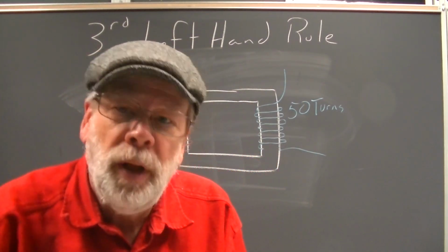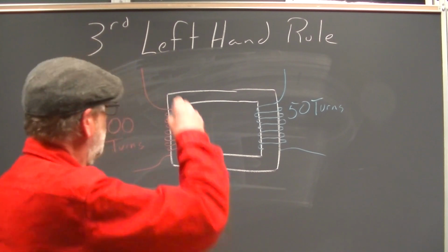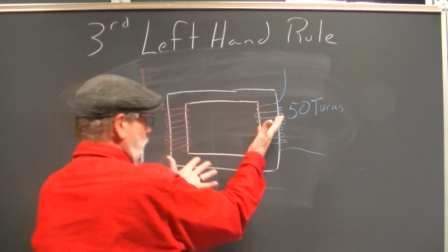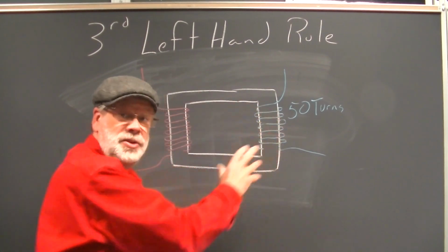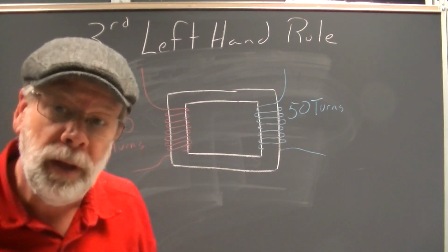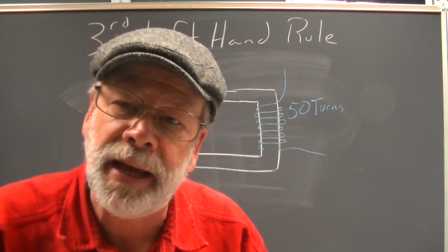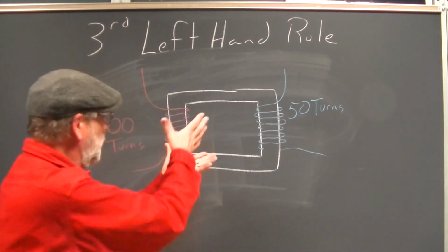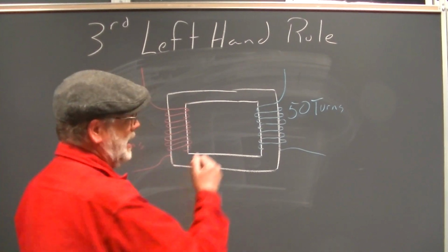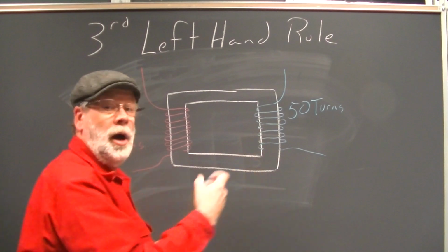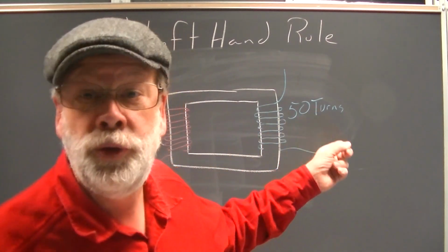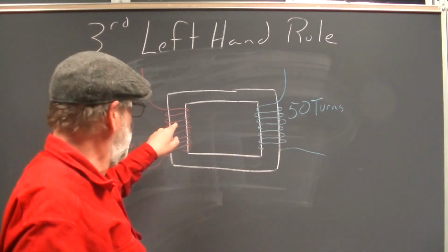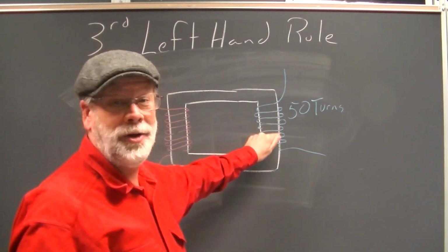As we get our first pulse of AC here, the current is coming this way, and we generate a magnetic field that wraps around, and as the magnetic field passes through that secondary coil, it generates a current in the secondary coil. Then we turn off the current, so we shut the current down. Now, again, as the magnetic field shuts down, current is again induced in that second coil. Okay, so the current here is creating a current there.